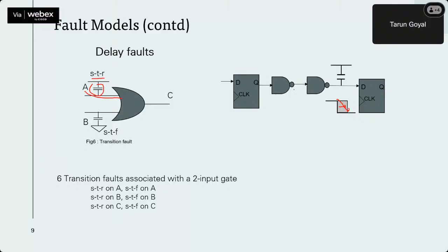So suppose this was the path, and then there can be a path which goes through one AND gate also. So suppose like this, right? There is an OR gate, and this is also a valid path from the launch flop to the capture flop. This is also a valid path. So in terms of path delay, we are trying to find out a particular path. We are looking for this launch, then gate one, gate two, and then the capture flop.